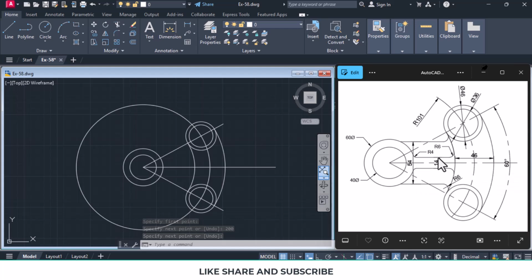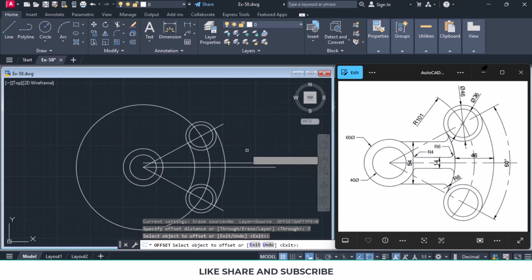Now we'll offset that line upward 7 units and downwards 7 units. So total is 14. So we say offset and we give the offset distance as 7 units. Select the object to offset, side to offset, object to offset, and side to offset. So this total distance is 14 units.